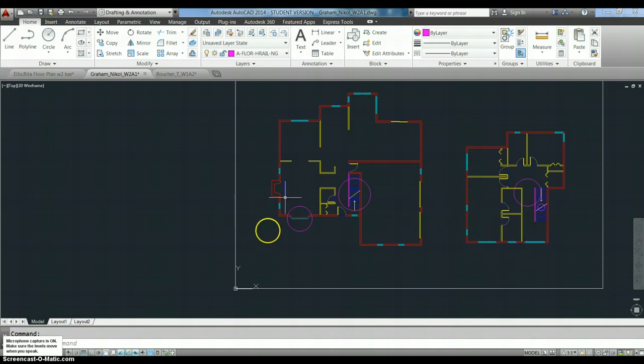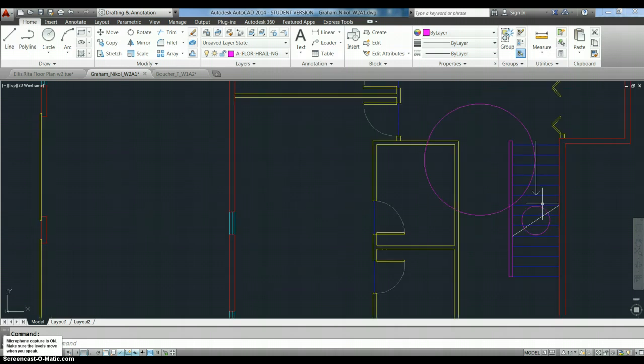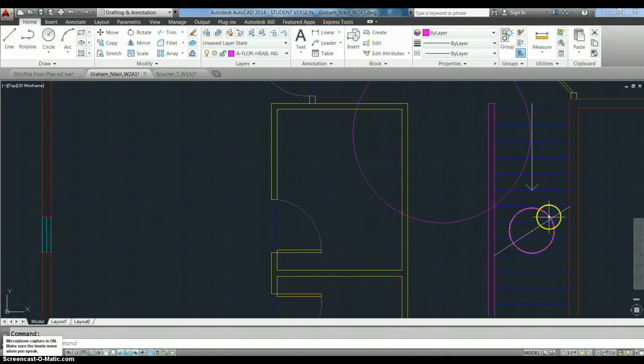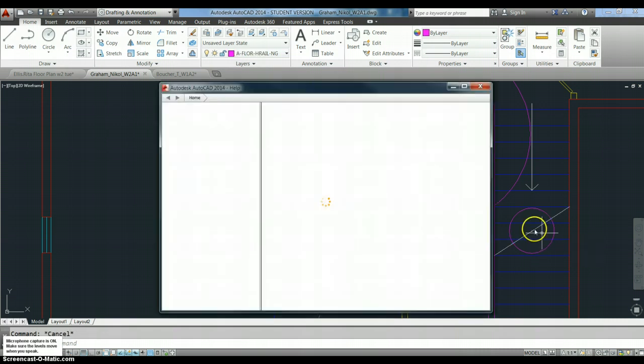Where I can see that you definitely had a challenge was this bay window, and we'll get back there in a second. I wanted to draw your attention to a couple of other little things. As I've mentioned to others, how you work with the break line here is a matter of choice of whether you put one in. If you are going to put one in, it needs to be bigger. This is probably scaled to the default size, which was 1/2 inch.